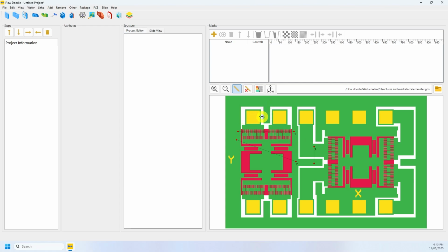You can draw more than one line to highlight different regions of interest. Here we will run a line through the comb drive and a second line through the pad area. If you are not happy with the line position, you can drag either endpoint or delete the line using the Cross-Section Delete tool.